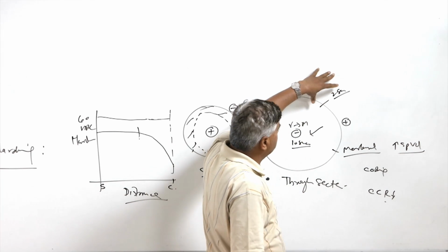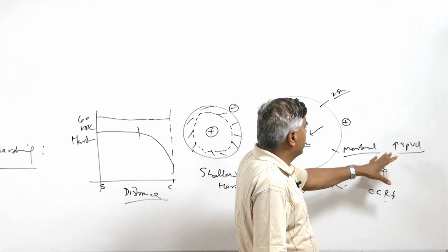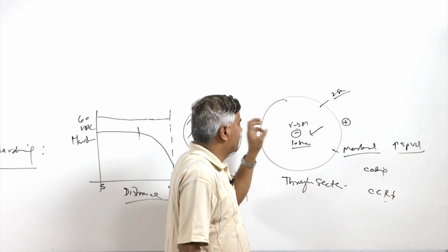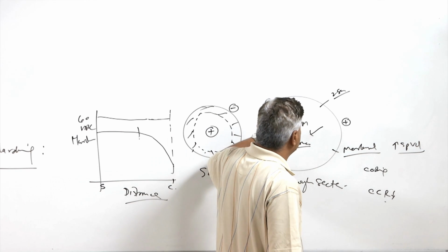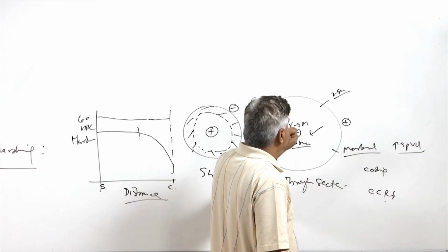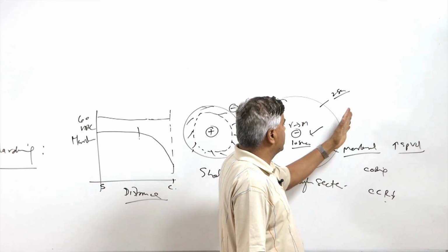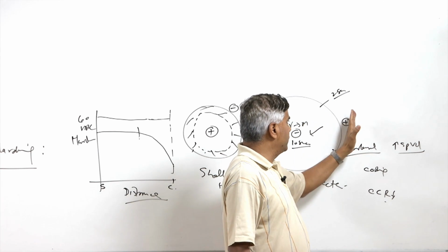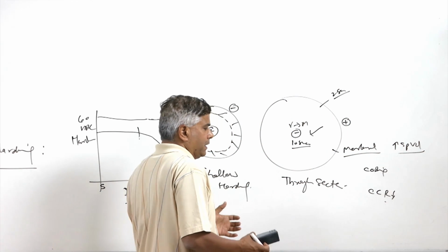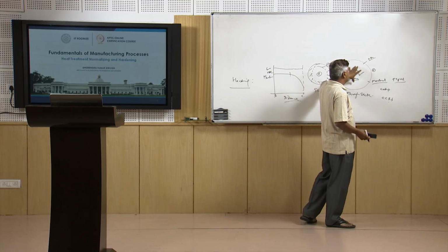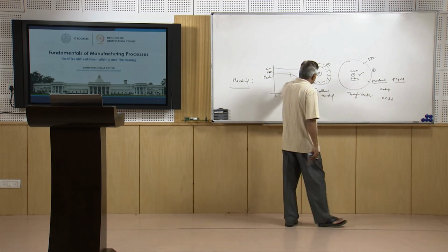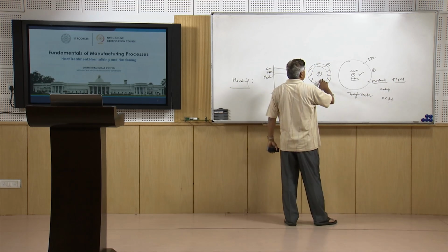So the first transformation occurs at the surface, forming the martensite, which is very hard and brittle, and subsequently the transformation occurs at the center with the increase of specific volume, forming the hard and brittle martensite. So this increase in specific volume causes the development of the tensile residual stresses at the surface, because it cannot relieve the strain being experienced because of the increase in specific volume at the center, since it is hard and brittle. While in the other case, just the reverse happens.